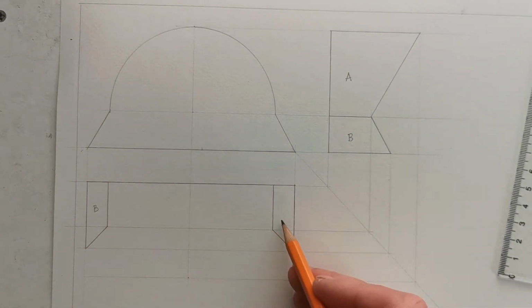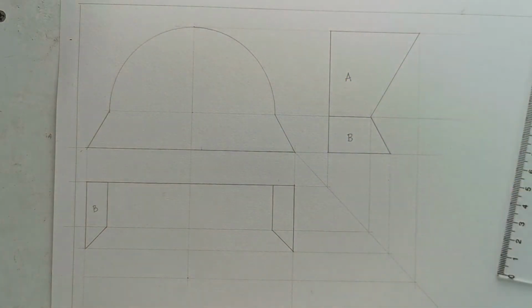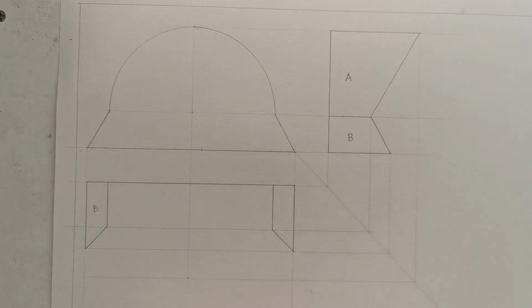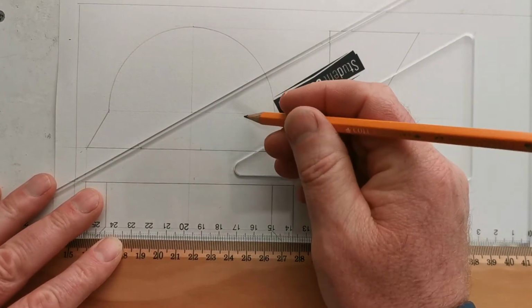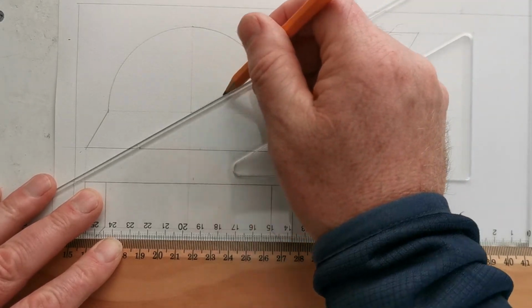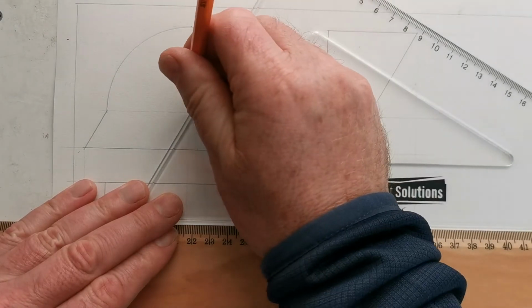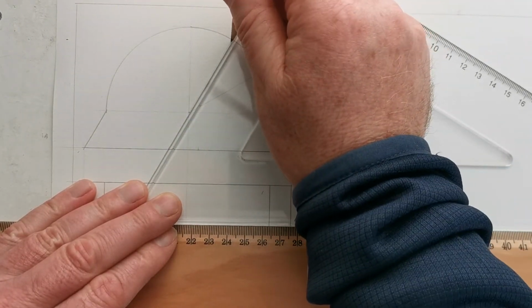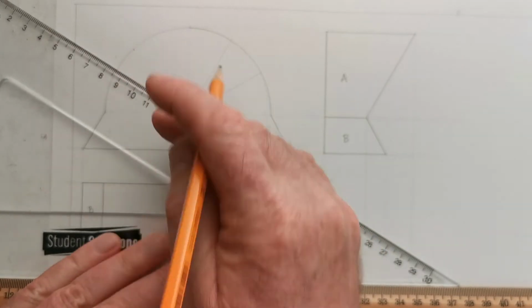I've done the flat surfaces, but I don't have the curve done, and the curve sticks out. So what I'm going to do here now, just work through it nice and slow, is divide up that curve into 6 equal parts. Now it doesn't have to be equal parts, but I just will, because we're going to use that later for the development then. So break that up into 6 equal parts.